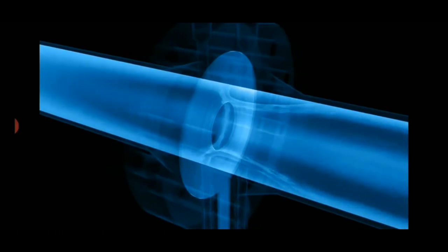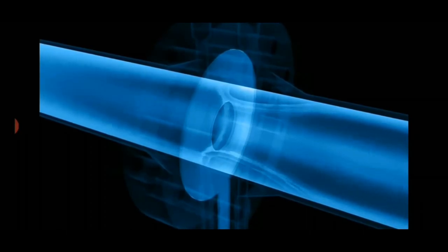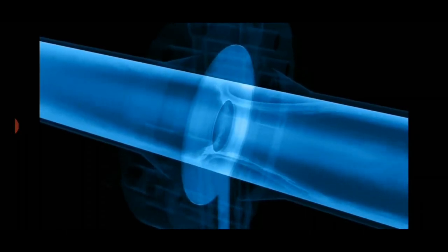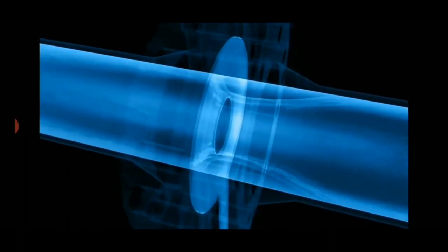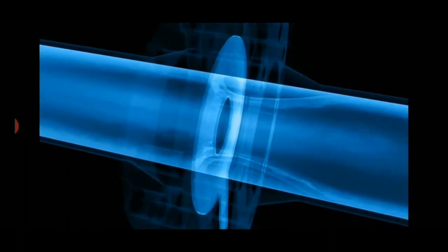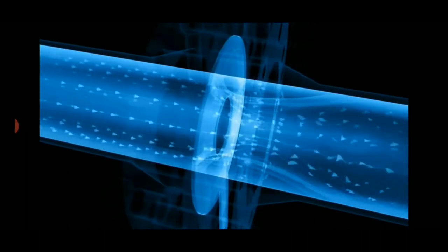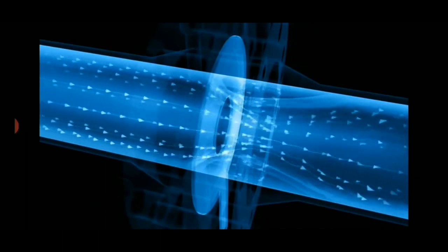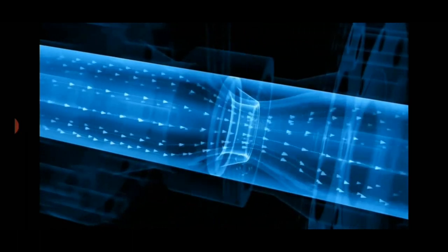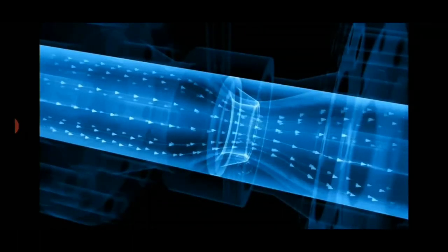Accordingly this differential pressure is sensed by the diaphragm element, and whatever we get from the diaphragm is further processed and we get the electrical output. So easily from this arrangement we can determine the liquid flow rate, or we can also find out the liquid level of any tank or something else.